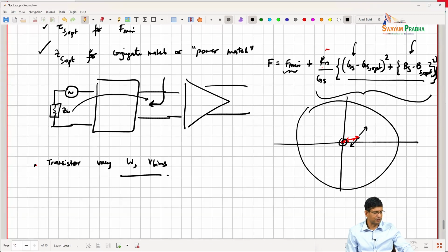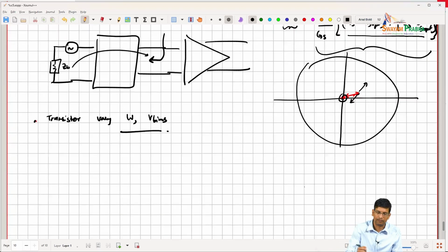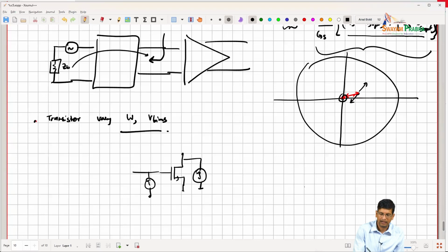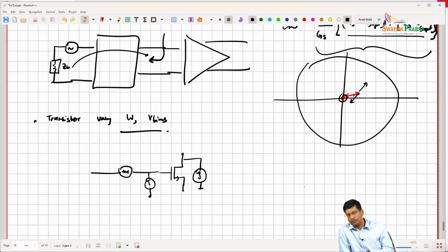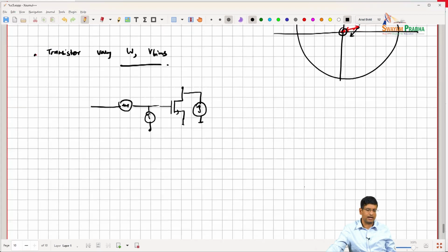Several textbooks have these parameters derived. In the transistor itself, we have primarily sources of noise related to channel thermal noise, and then you have gate noise, and some noise because of parasitic gate resistances, right? There are papers that derive what these parameters are based on these metrics. We'll take a more millimeter wave algorithmic approach, right?